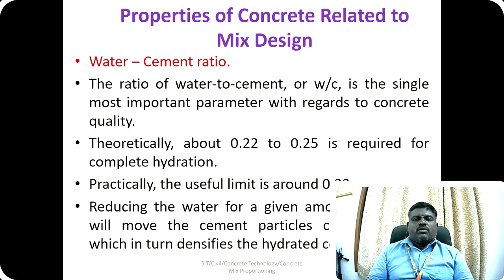Alright. So if we use a higher water cement ratio, then the strength of the concrete is going to be reduced, right? At the same time, when we reduce the water cement ratio, it will lead to an increase in strength. At the same time, the workability of the concrete will be decreased. So reducing the water for a given amount of cement will move the cement particles closer together, which in turn densifies the hydrated cement paste.